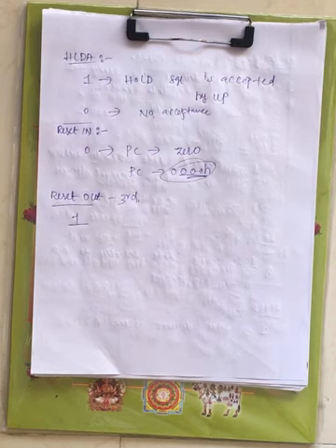Now let me briefly explain. HLDA stands for hold acknowledgement signal. What is meant by the hold signal? It gives the information to the processor that other devices are requesting access to the address bus, data bus or control bus. Whether to accept the hold signal or not is up to the processor.